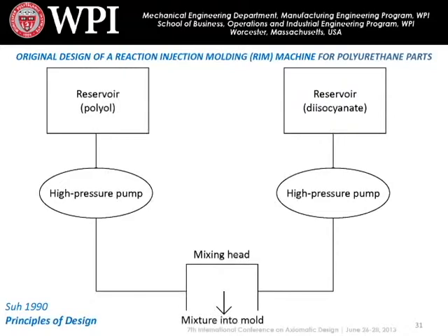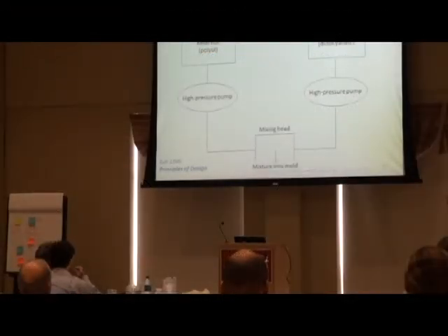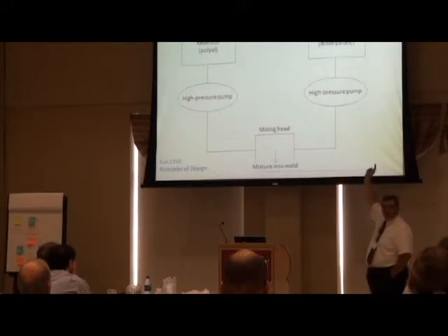The way these things work is you fill one reservoir with a really expensive polymer and another reservoir with another really expensive polymer. And when you press the two together under pressure, dashboards for cars come out, and furniture that goes in your backyard. The functional requirements are that we have to mix the correct amount of these two things together for a certain amount of time and pressure, and then we end up with the parts that we're going to make.